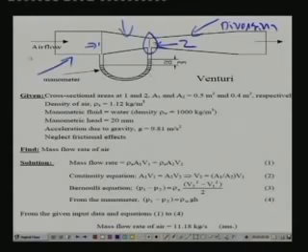So, basically the air flows through the venturi, and because of the air flow there will be some pressure difference in the manometer, that means there will be a manometric head here. And from the characteristics of the venturi and by measuring the manometric head, you can calculate the air flow by applying Bernoulli's equation. So, now let us look at the problem statement.